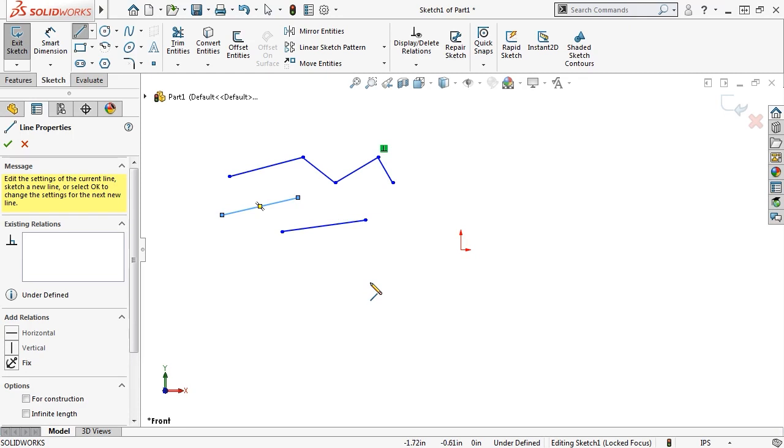Let me clear this sketch by deleting these lines. To delete sketch items, all you have to do is select them and press Delete on your keyboard. This can be an annoying stumbling block that trips up many new users. To select something in SolidWorks, you click on it. However, because I still have the line tool activated, when I click on these lines, I end up beginning a new line. Typically, a new user will notice this, and to try to avoid this new line, they will bring their cursor back to the beginning very carefully, hoping that SolidWorks will forget all about the new line.